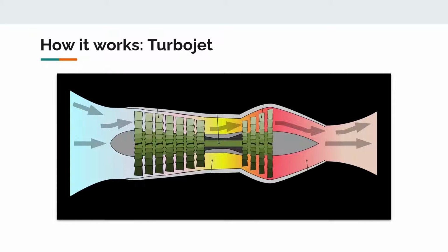This picture right here is a typical turbojet. I think we're all to some degree familiar with how that works. We have the inlet, compressor, combustion, turbine, and nozzle. Turbojets use all the air intake for combustion, which means all the power produced by the gas turbine is used by the compressor. Thus, the output of the turbojet lies in the energy of the exhaust gases as opposed to the shaft power. However, with this configuration, there is an inherent inefficiency regarding fuel consumption.